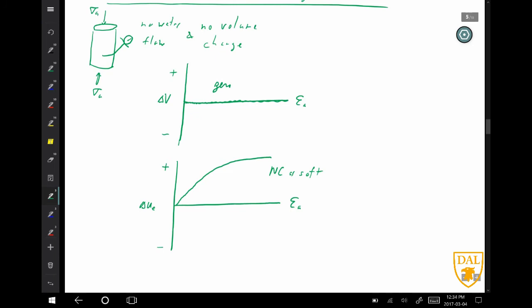Okay. Now, if you think about what the drain condition was, it wanted to contract, right? So the voids wanted to contract. In this case, when no water is allowed to flow in or out of the voids, this tendency to want to contract kind of results in sort of pushing of the grains on the water in the voids. And that causes the pore pressure to want to increase during shearing.